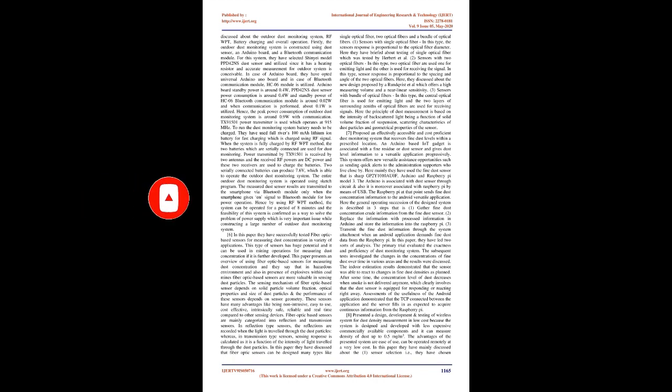The sensing mechanism of a fiber optic based sensor depends on solid particle volume fraction, optical properties, and size of dust particles, and the performance of these sensors depends on sensor geometry. These sensors have many advantages like being non-intrusive, easy to use, cost-effective, intrinsically safe, reliable and real-time compared to other sensing devices. Fiber optic-based sensors are mainly categorized into reflection and transmission sensors.